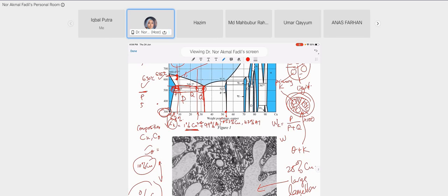For example, now you know why the mechanical properties of your alloy have not achieved your target. So what next is having a higher lamellar structure. How to get more portion of lamellar structure is by having a higher alloy composition. For example, you take 30%, or maybe exactly at the eutectic composition. So you can have 100% eutectic structure. Something like that.